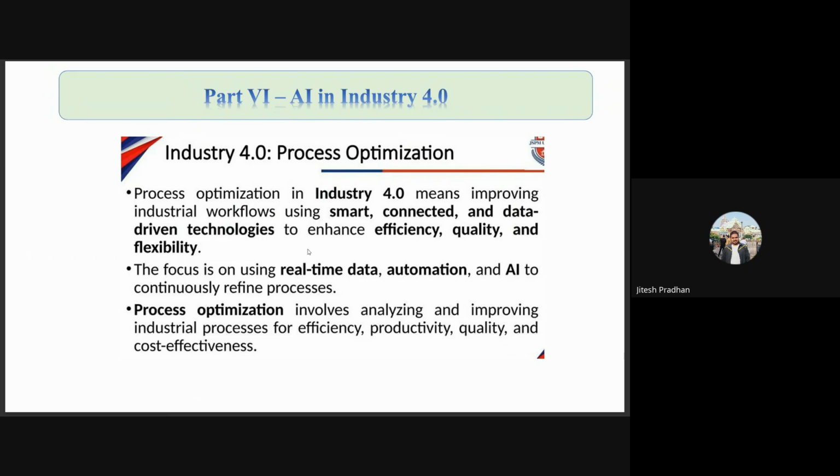Okay, so how can we do that? Basically, a high shutter speed camera will be installed. The camera will be taking continuous pictures of the steel sheet, or we can call it a video. Videos are nothing but pictures with a frame rate. From the pictures of the steel sheet, by applying some pre-processing, we try to find the edges of the steel sheet. If the edges are not properly aligned, or there are deformities, then it will monitor the deformities, and within 12 seconds it will inform the control room that deformities are present.